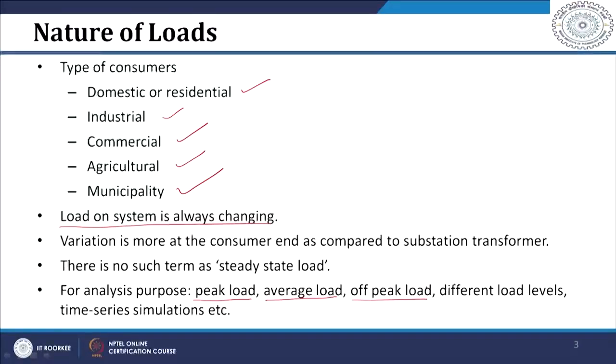If you want to do some more sophisticated analysis, they use different load levels, meaning in a day the whole load curve is divided into 4 to 5 different load levels. So, we can analyze at different load levels, and if you want further accuracy in the analysis, they use what is called time series simulation, where you can do the analysis at a number of instants over a day. Say if you are measuring the loads at each 15 minutes, you can do analysis at each 15 minutes, then it will become your time series simulation.